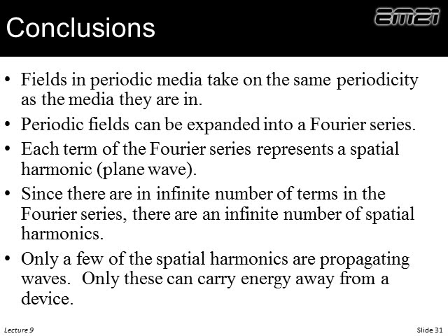Conclusions from all this. Fields take on the same periodicity as the media that they're in. Periodic functions can be expanded into a Fourier series. Each term in the Fourier series represents a separate plane wave or spatial harmonic. There's an infinite number of terms in a Fourier series. So there's really an infinite number of spatial harmonics. It's just that power usually only ends up in the lower order harmonics, not the higher orders. And when we numerically solve things, we clearly only retain a few of the lower order harmonics. And it's only those that can transport energy away from the device. But those cutoff modes are important within the device, telling you how things will behave.